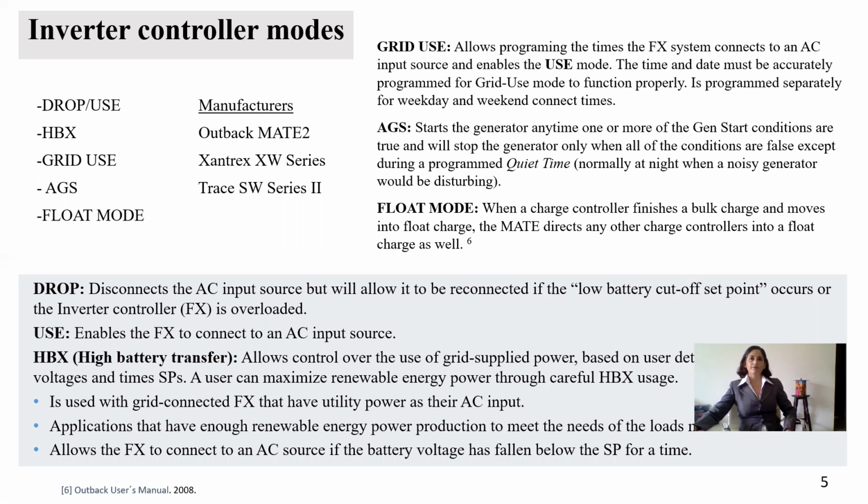The float mode. When a charge controller finishes a bulk charge and moves into the float charge, the Mate or inverter controller directs any other charge controllers into a float charge as well.